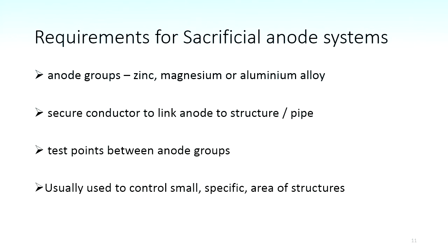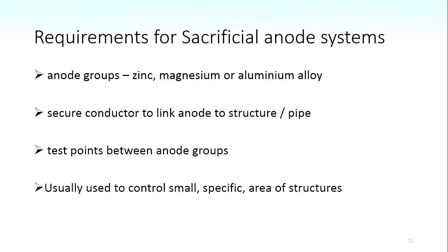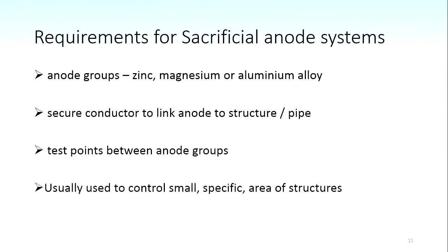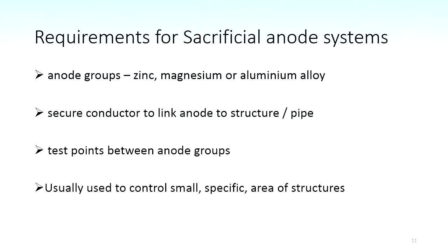Yes, sir. With the limited, yeah, so your mass transport limited, so the oxygen diffusion goes off like that. It looks like you get a much better ratio, a reduction of corrosion current to applied current. Well, E-corr and I-corr are depressed.